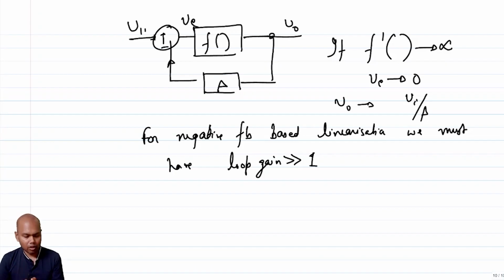If you have done analog circuits negative feedback loop design, you will readily relate to this. It is not trivial to make high loop gain negative feedback at higher frequencies, simply because you have these capacitors which steal current and load your various blocks, and it reduces the loop gain, right? And there's a classic trade-off between stability of a feedback system and the bandwidth at which you can operate it, right?